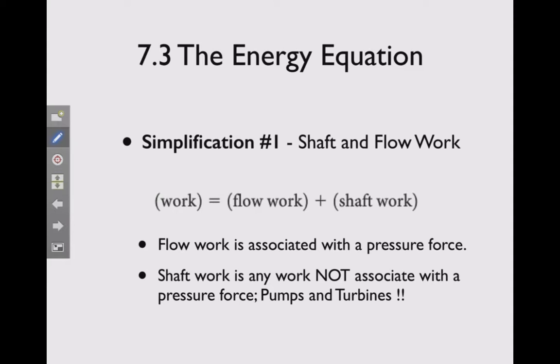The first simplification is the separation of the work into what's called shaft and flow work. The flow work is associated with a pressure force. If we have a pipe and a control volume in it, there are compressive pressure forces on either end of the control volume. This is really what we're getting at with the flow work, and you'll see in a minute that flow work turns out to depend on the pressure.